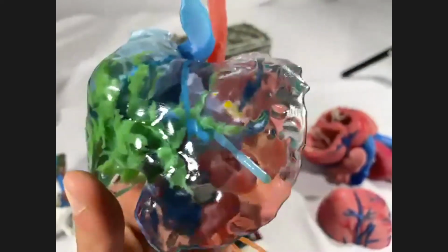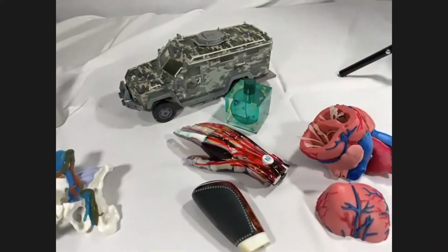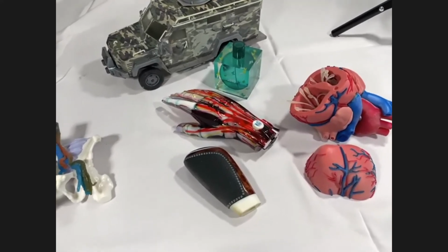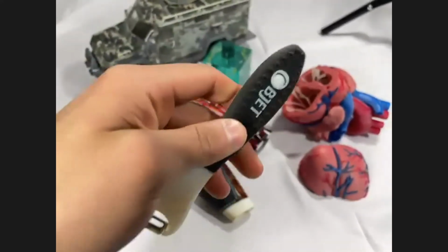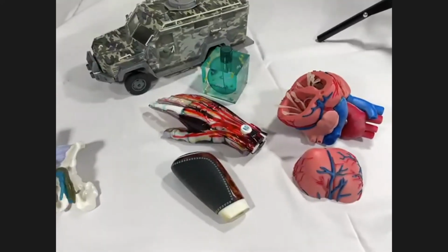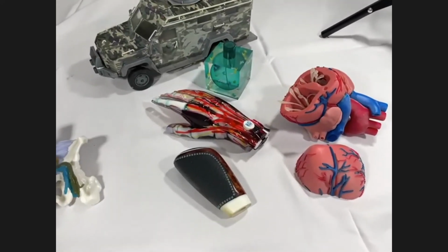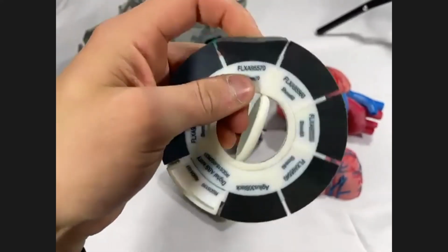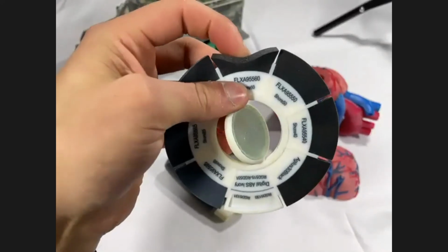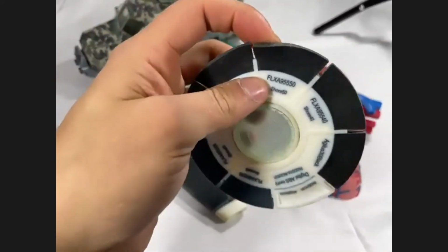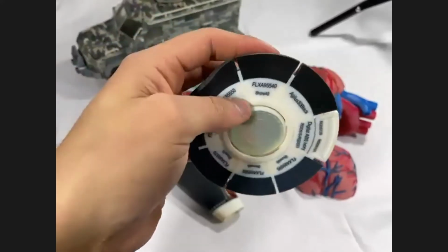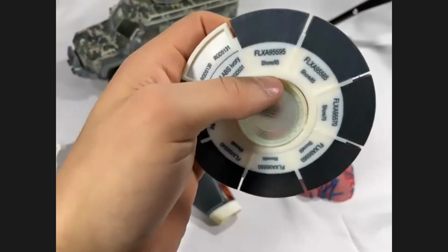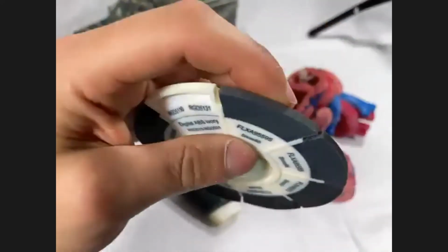Matt, another question. Can the rubber-like material have a different feel all the way up the handle? I think I would need a little bit more information from that question. So the shore values that you select will be throughout the part. Now, it will have a different feel depending on the thickness of it as well. So you might have a Shore 95 that you can flex somewhat if it's maybe 2 millimeters thick, but if it's like an inch block, it's not going to flex a whole lot.